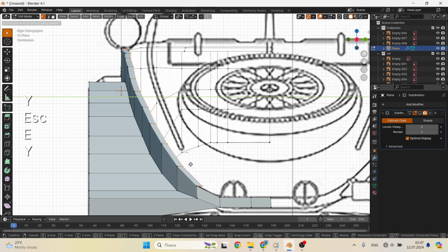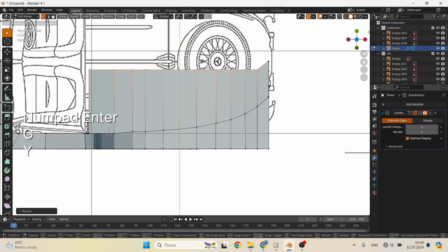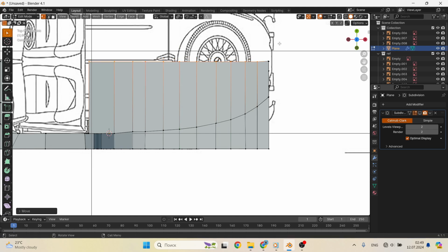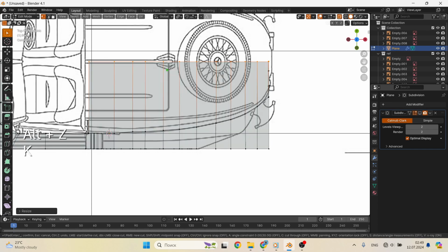That is, based on the already finished high polygon form, a low polygon mesh of the gnome is created, which is very convenient and easy to animate. And all those details from the high polygon version are transferred to the low polygon one using various techniques, for example, displacement or normal maps. Sometimes they use the abbreviated spelling, retopo.